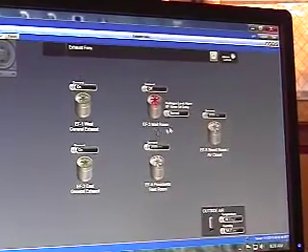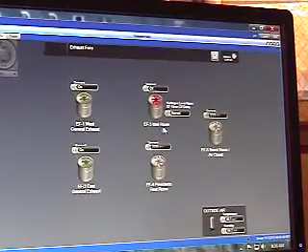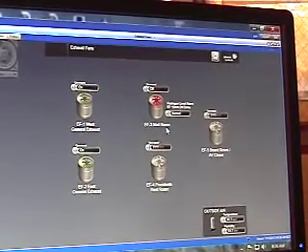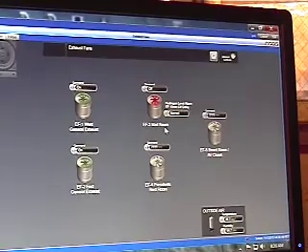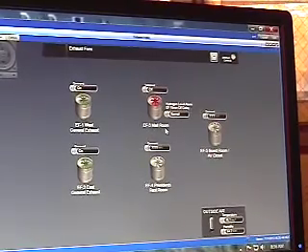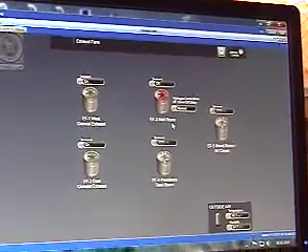The mailroom exhaust fan here is the one in that cart charging room. Ideally, this fan will always be off. What will happen is if the hydrogen gets too high in that room due to the battery being charged in that cart, it releases some hydrogen. If it gets too high, you'll actually get a buzzer in that room going off, and then it'll enable that exhaust fan to turn on. You'll also get an alarm notifying you that something's going on there.